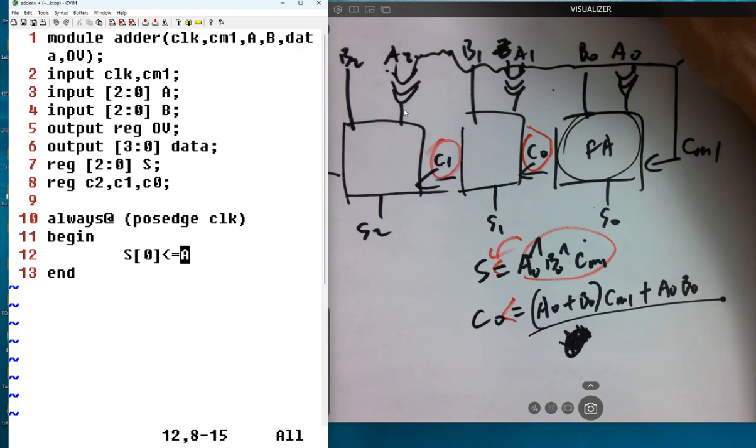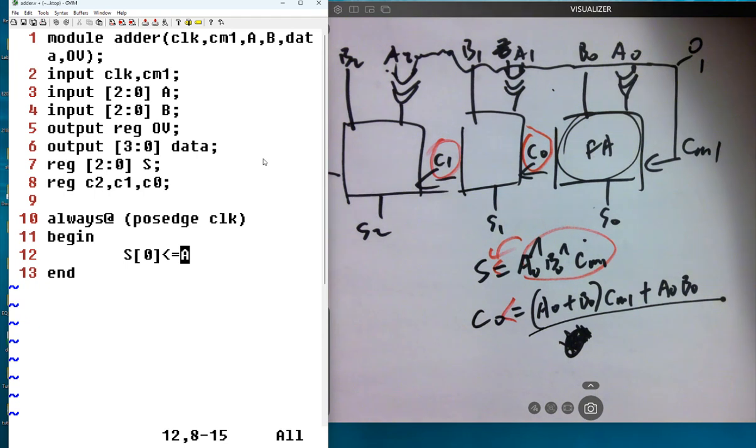Even though you don't see anything, to implement into the FPGA, you need a register type as intermediate data over here, because you are having the C-1 and A2 being XORed, and eventually you assign it to another one. You need to hold the value over here. So you need a name for this net. If this is considered a net, you need a name for it. So we find that, hey, we need a name for that net.